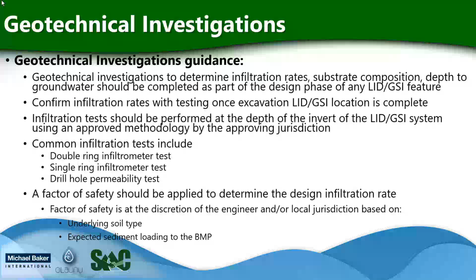Geotechnical engineers will integrate a factor of safety that should be applied to determine the design infiltration rate. The factor of safety is at the discretion of the geotechnical engineer or the local jurisdiction. And that's really based upon the underlying soil type and the expected sediment loading for that particular BMP. Essentially, what does the drainage area look like?